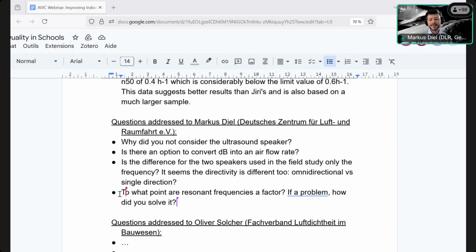After we realized during our first measurement campaigns there that a lot of sound just travels through the walls, we soundproofed the test bench. So I think we just got rid of this problem by soundproofing it. And in an actual building, you don't have this problem just because walls are so big. And since you're using white noise, I don't think that resonant frequency has ever influenced our measurements, at least that I know of.